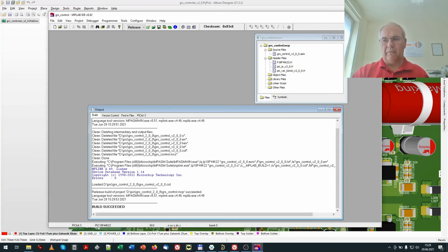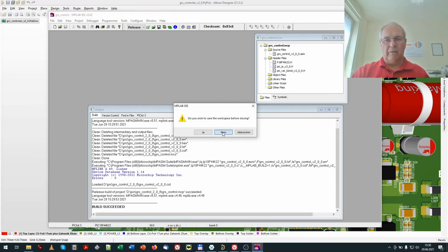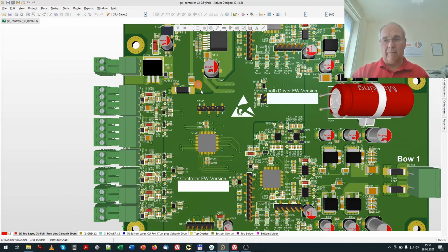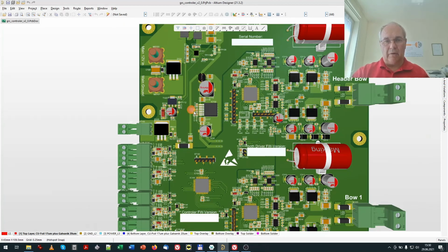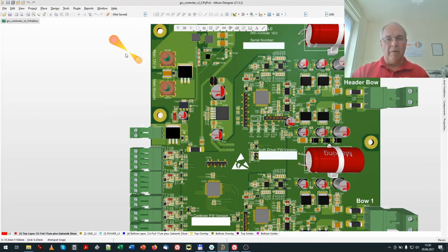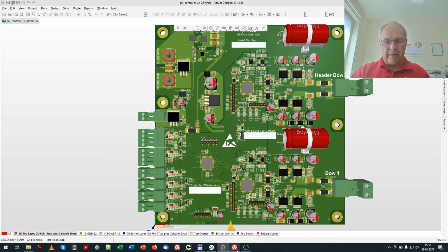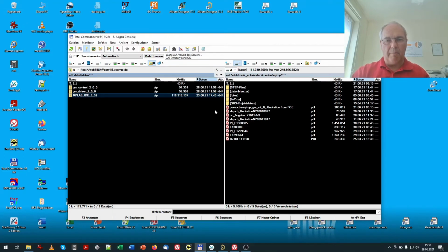You can plug off. Before you can program the board, you will connect the 12-volt supply here and enable the ignition connector for supplying the board. If there is a failure in the PICKit, that could be the reason, because this is important.